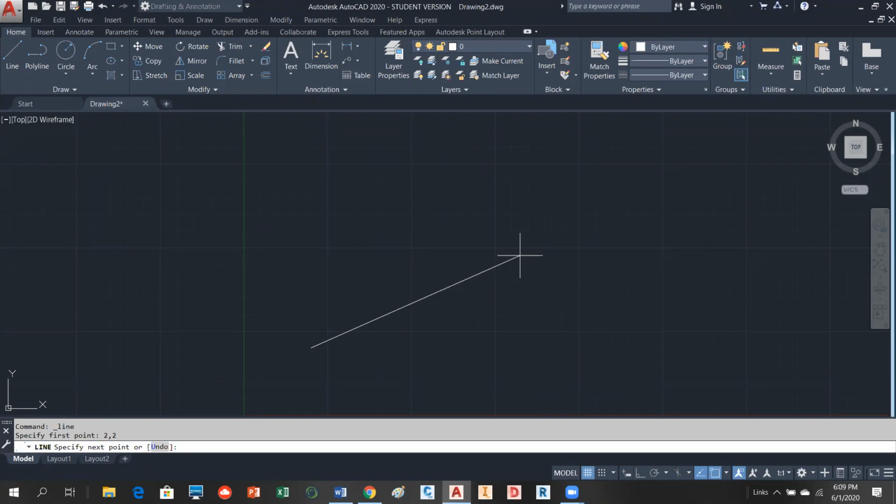This time you're going to type in the @ symbol. So I shift and then the character 2 gets the @ symbol. We're going to tell it how much to travel in X and how much to travel in Y from the point we're sitting at. So if you look at my diagram, you'll notice that we are 6 units over from A to B. So I would type in 6, and then my Y value, there's no change in Y. So I'm not adding or subtracting anything to it, so I'm just going to go 0. Question, anybody?